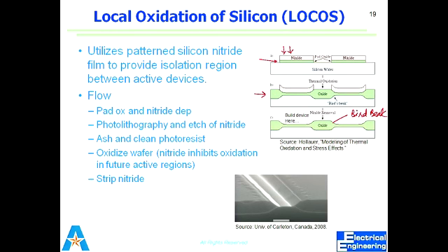So what does that mean? From this end, 500 nanometer comes in, from this end 500 nanometer comes in. So it means there is no more active area. You lose your active area. So in the case of bird's beak, the active area should be larger. I need to make sure that my active area is large enough that due to the bird's beak, the active area does not disappear, because that bird's beak encroaches from both sides.